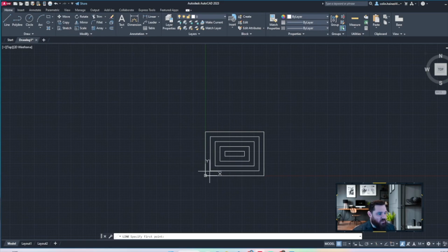I know that distance. I know I could go 1.1 and then go 5 over and find the midpoint that way, but it's a lot easier to allow AutoCAD to do that math for us. And it will if we go down here to the bottom and grab O snaps, or object snaps. It's this on the very bottom, this little square with a little blue square on it. I'm colorblind, I think that's an orange square on top of it. So we're going to go ahead and click that.